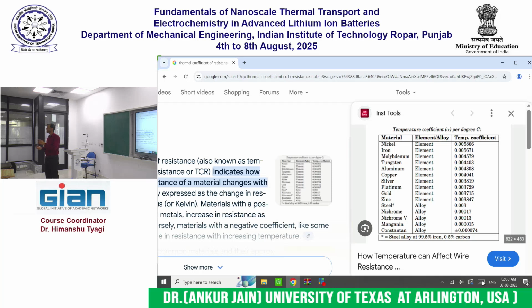In fact, the same thermal runaway problem, right? If this temperature coefficient of resistance is very high, then what will happen is it gets hot, its resistance increases, so it generates even more heat, because of which it will get even hotter and so on, right? That is the reason why these numbers are designed to be so low. But anyway, in order to design my temperature sensor, I would like a high value of alpha, and so nickel or iron are probably good candidate materials for that sensor.